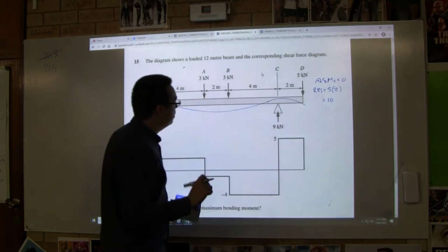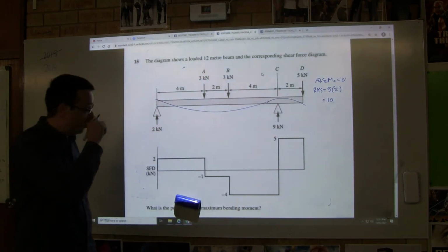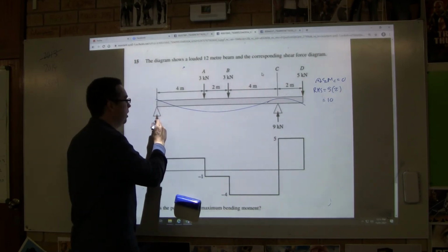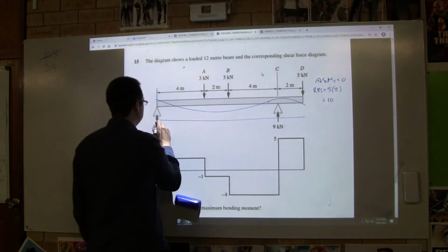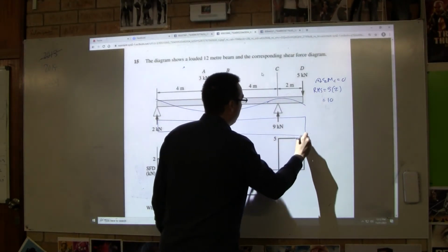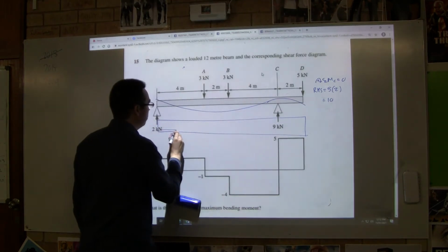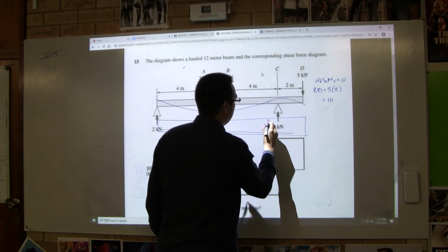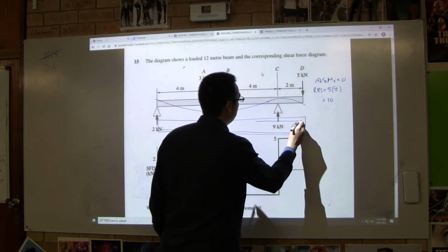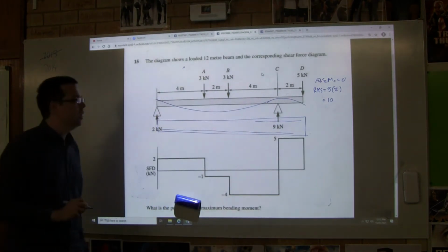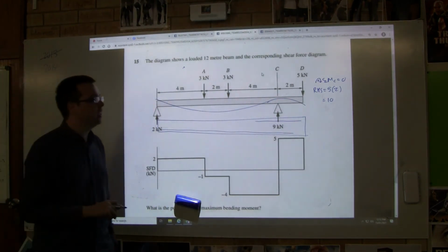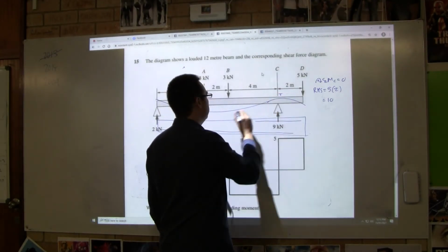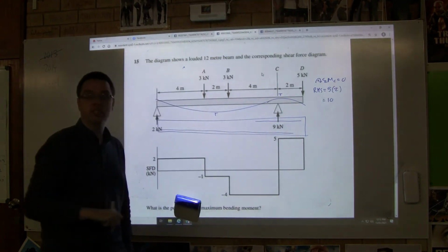The thing is, if you're designing for concrete, here's how concrete works. I'm only going to say this just because I have questions that have sort of discussed this. If this was a concrete beam, I've drawn a bit wonky, but forgive me. What we would do is we'd have steel running along the bottom of the concrete beam. Even here, we'd still have some. And then we'd only put steel at the top of the concrete beam there, likely. A bit complicated because steel always goes on the bendy side, on the side that's being stretched, this is where the tension is. So we put steel where the tension is.